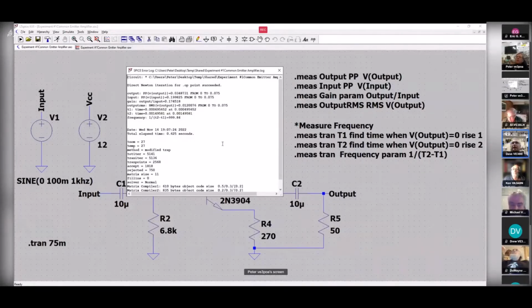But the other thing too is LTspice defaults to a low floating point precision. So what you're seeing there is round-off error. If you go in, there's a numdigits parameter, right? That if you set, it'll increase the resolution of your numbers, and you may see it round up higher. But if you were to round this to 2 or 3 decimal points or to an integer number, it'll come out exactly what you expect it to be.